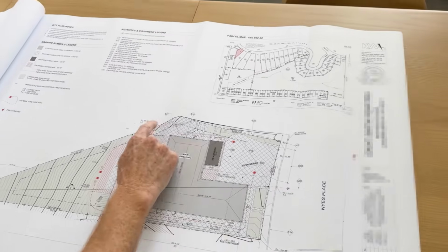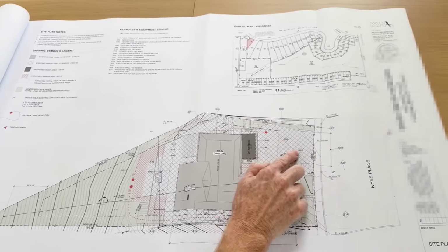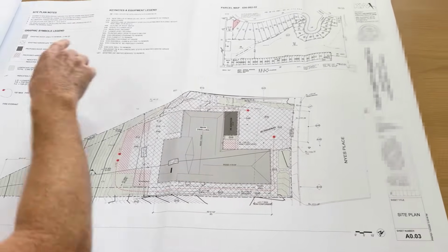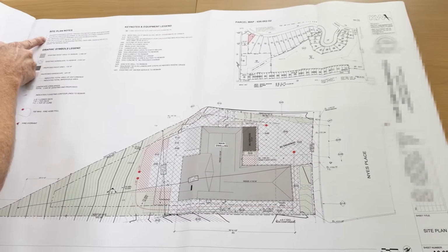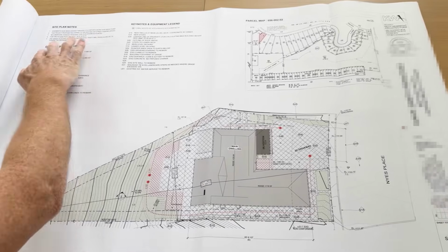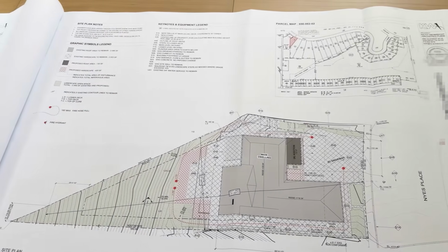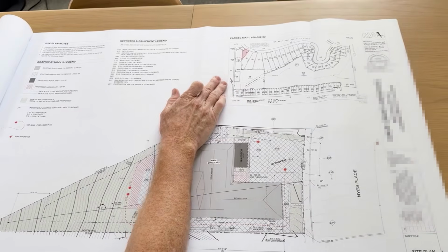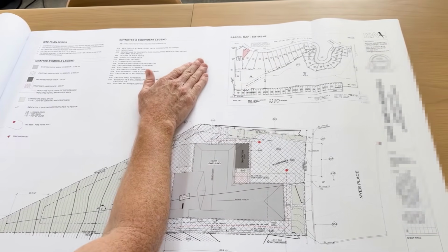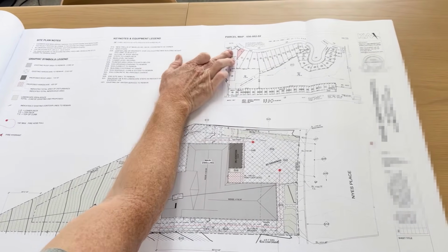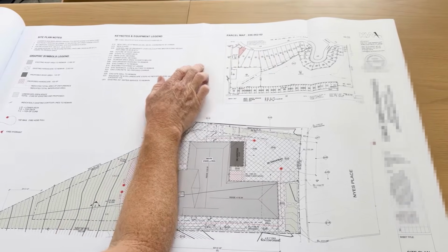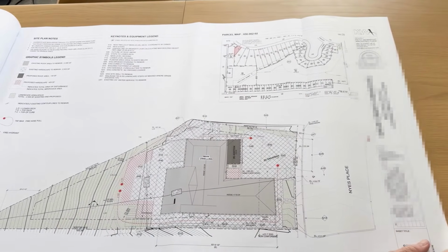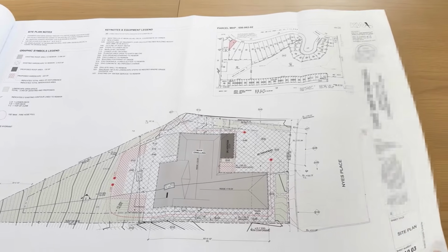So as we go around, you just want to pay attention to all these different pieces of information. This is our site plan, okay? General notes, site plan notes will be up on, usually somewhere. And again, assistance on identification. In this case, the parcel map has been uploaded and added to the drawing, okay? So we can get an idea of how the lot is shaped, how the other lots around it are affected, et cetera, et cetera. So that's your site plan.